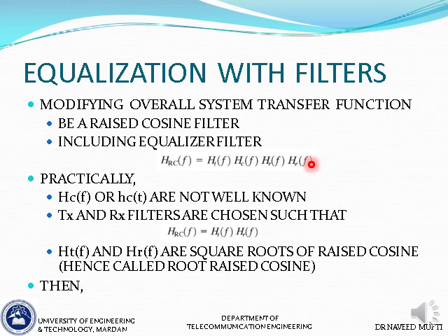So basically what happens is that the channel and the equalizer become reciprocals of each other, and so the equalizer transfer function is 1 over the channel transfer function, and we know the expression for the channel transfer function. If we include that, this is what it looks like. This is the equalizer transfer function needed to compensate for channel distortion, which is simply the inverse of the channel transfer function.